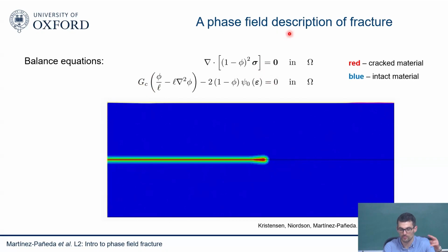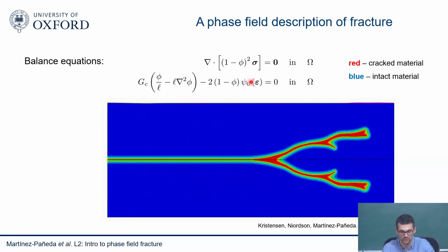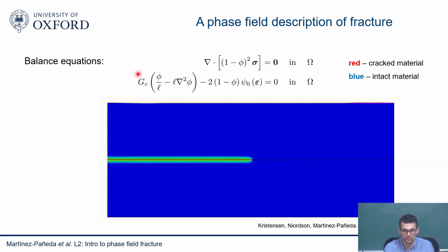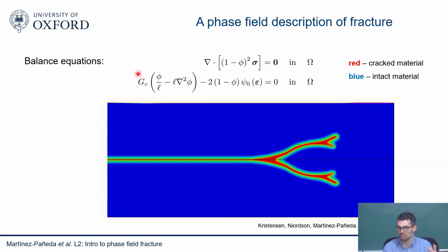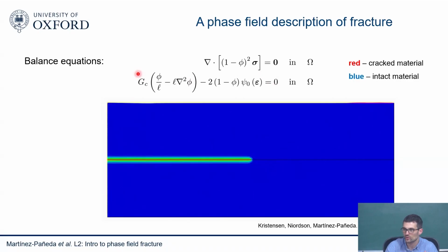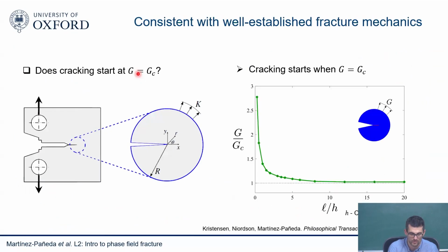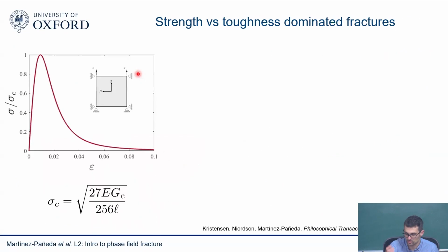So that's the benefit. You're solving independently, so that has some computational advantages. And the other one is that you only rely on one parameter that has a clear physical meaning that you know from a fracture test, and you connect damage and fracture mechanics very well. I think those are the key advantages, I would say, versus non-local continuum damage mechanics.